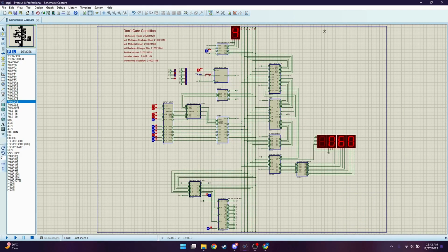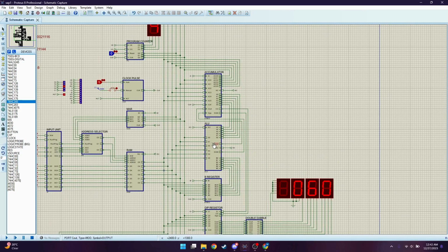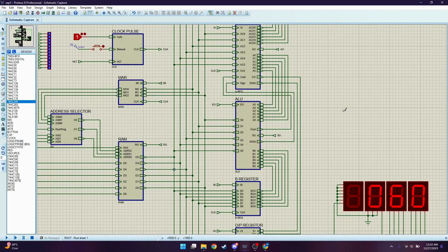Arithmetic and Logic Unit or ALU is a combinational logic circuit that is capable of 6-bit binary addition and subtraction. There are two control bits called addition/subtraction select or SU that decides when to perform addition operation or subtraction operation, and ALU out, that is called EO. It puts all the ALU output onto the bus, and output of the ALU should be disconnected when EO is low.